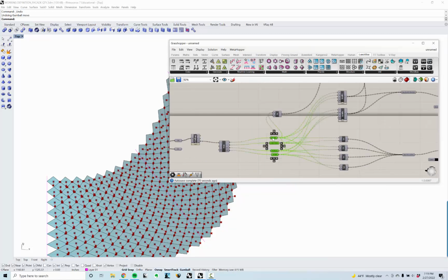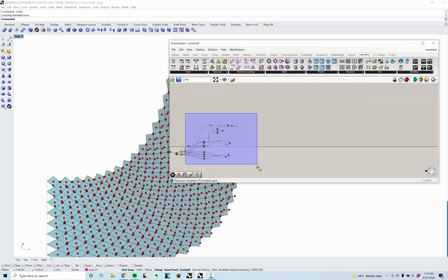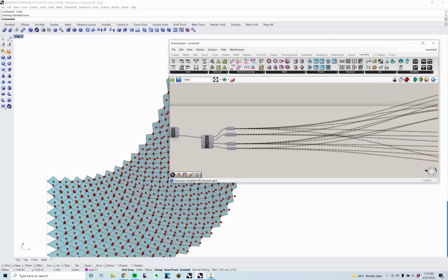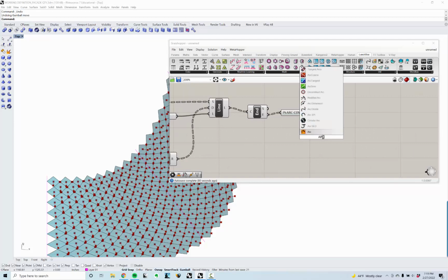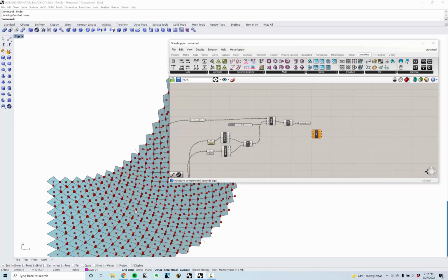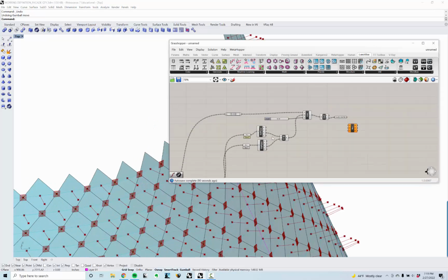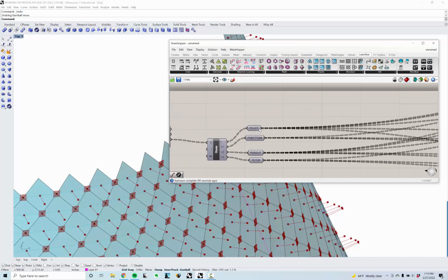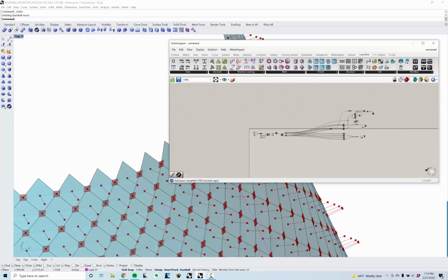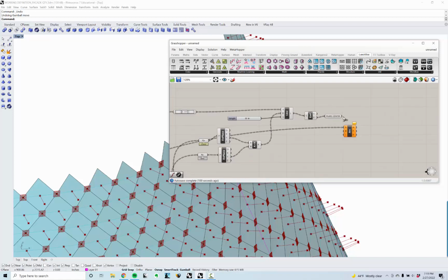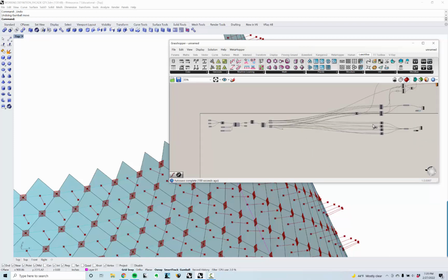Like when I've done that here, I can essentially create a line between the end of this operation and the beginning of this one. It's because I'm just working with these points now. So I can define what that is, and then I'm going to do an arc 3 points. I want that arc to go from the top to the bottom of the panel and go through there. So my arc start point is going to be the bottom. The middle point is going to be the arc center, and then the end point is going to be the top.